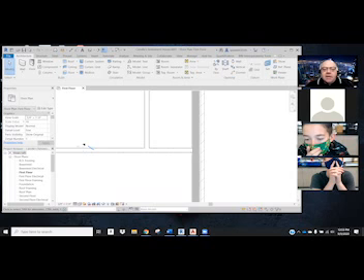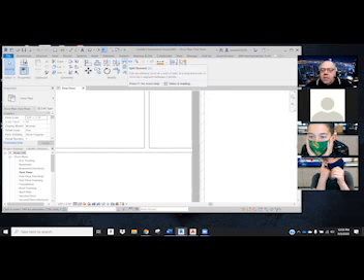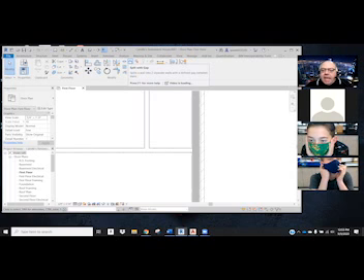So let me erase that out because it bugs me. And the close down. So I need to do a little surgery to my walls. Okay. So I'm going to go into my modify tab. And when I get up here about in the middle, there's these 2 little guys. They're really small right next to the thumbtack, the pin button. One says split the element. The other one is split the element with a gap.